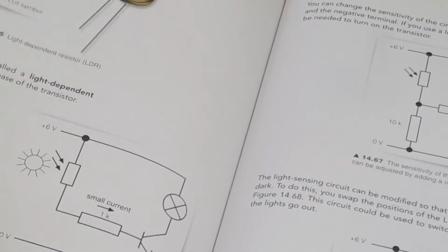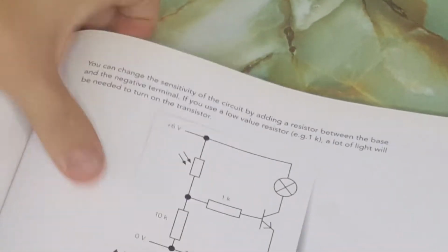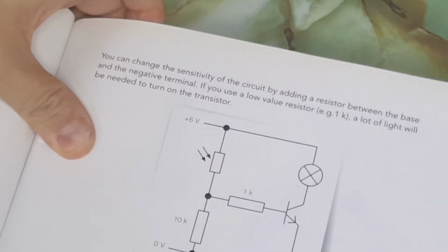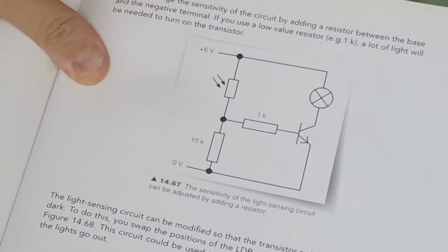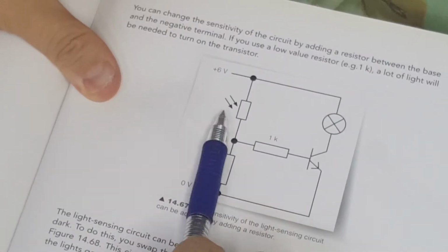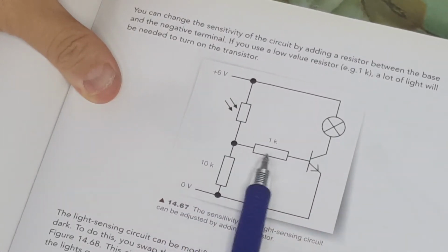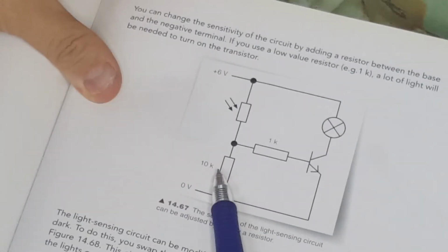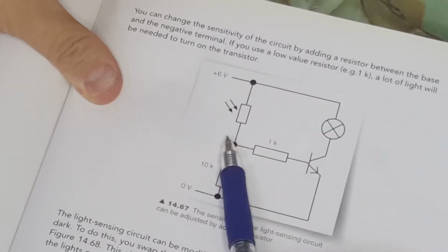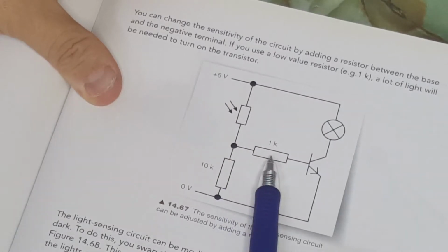Now this is not what we want for these two. We want to be able to control, all right, using the LDR. So if you look at this configuration on page 289, when there is light shining, current will flow through and some will pass through here, the rest will go through here. Between 1 kilo ohm and 10 kilo ohms, the current is not stupid, all right? It's smart enough to know that current basically flows the path of least resistance.